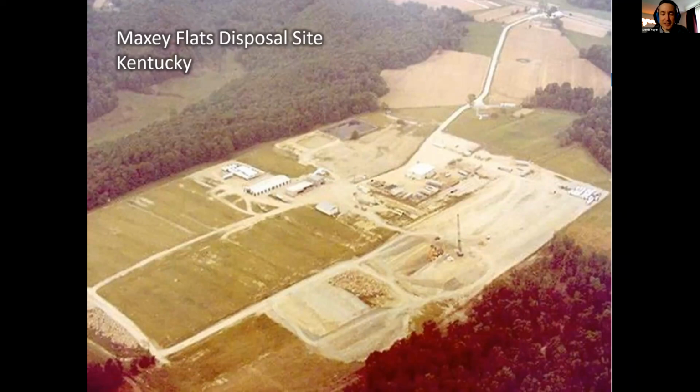So this would have been the mid-70s. And it shows a little bit about the situation of the site. So it's located on top of a bluff. The surrounding terrain is valleys. And when it rains, any rainwater that strikes the site will typically run off the cover and then down into the valleys on either side. Or, as turned out to be the problem here, it can also percolate through the top of these trenches where waste was buried, and then carry potential contaminants into the surrounding surface water, which is in fact what happened.